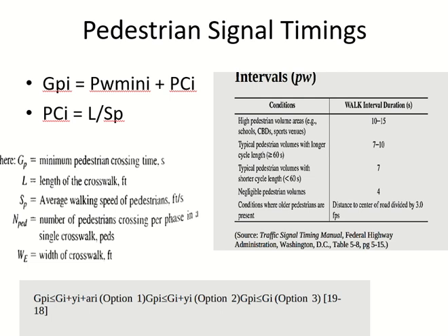And we are also assuming that the people behind them will stay. So clearance time can come from the length they have to cross over their speed. Length over speed gives you time, right? Distance over speed gives you time. So what is L? Length they have to cross. And speed, SP, is the pedestrian speed. For pedestrian speed we have some guidelines, normally 3 feet per second or 3.5 feet per second, like around 1 meter per second. Okay, around that value.